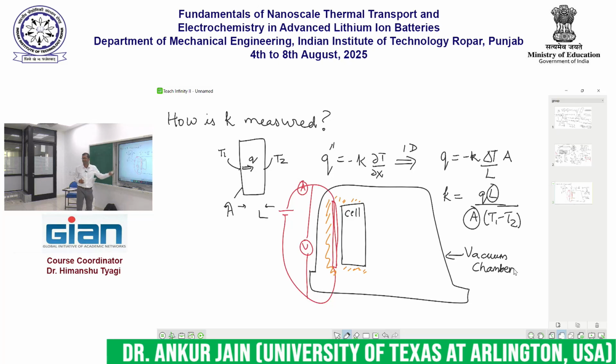All right. What is the next step? What do we do next? So we have some idea of this term now. A and L are easy to measure. We now need to measure the two temperatures, correct? Where do we measure those temperatures and how? Of course, you can create a number of nodes, a number of thermocouples on one side, a similar number on the other side, and take the approximate. So where would you like me to place our thermocouples? Here? On that surface, a number of them? Okay, sure.